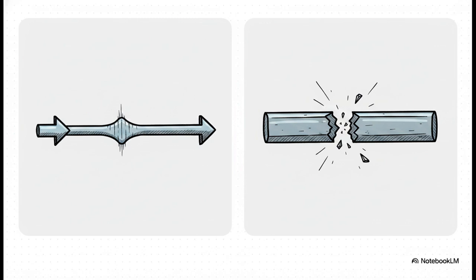However, brittle materials like cast iron behave totally differently. They don't have a well-defined yield point at all, they just suddenly snap. Therefore, for brittle materials, we have to base the factor of safety on the ultimate stress, the absolute maximum stress before total fracture. If you use the wrong baseline here, well, the results can be pretty disastrous.